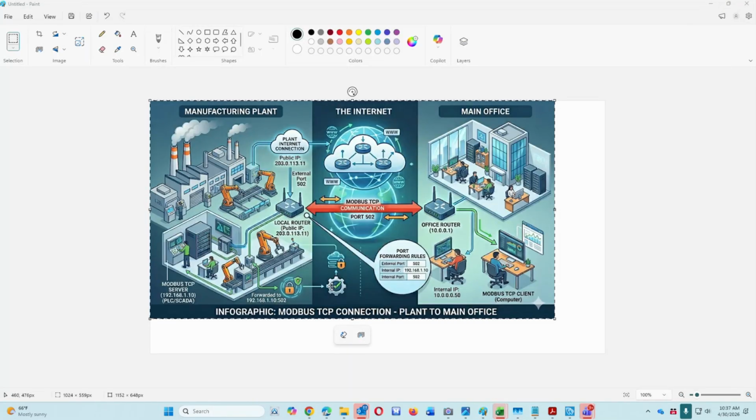Okay, so this is just a picture showing how a system would work remotely. So this is the manufacturing plant where everything's happening. There's a local control, and everything's done through Modbus RTU. Data is shared from the process through Modbus TCP to various locations through Ethernet switches and routers.